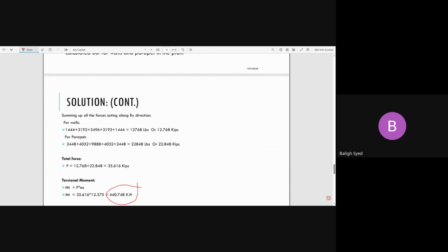This is what I usually do so that you can understand. First of all, you understand, and you can cross check. You have got to run the sanity checks on whatever results you are getting from the application, whether it is ETABS, SAP, STAAD, RAM, PT, RAM Concept, RAM Steel, RAM Advanced, all these software. None of the software is accurate, none of the software is correct until you check it by yourself. You get the satisfaction within yourself, and then you satisfy yourself, okay, this is the pressure I calculated by hand, and this is the pressure the software is calculating. Then it is correct.